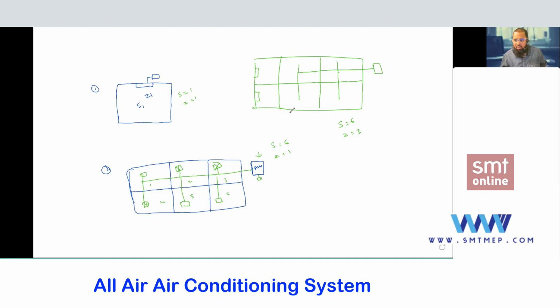Based on that, we can go for only one AHU, if that much capacity is available to connect all the spaces, because only one zone is required. For example, in a school, all the classroom timing and temperature is the same, so we can connect all these classrooms with one unit. But the admin area timing is different, so for the admin area you can consider a separate unit. So it is based on the application, right?